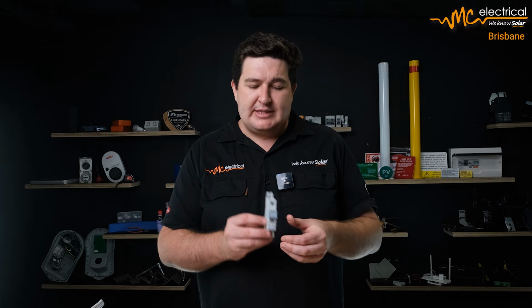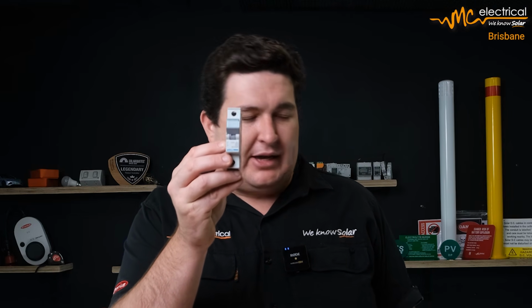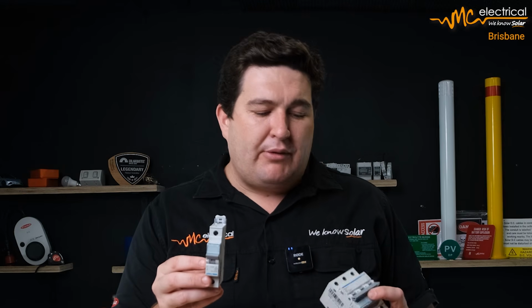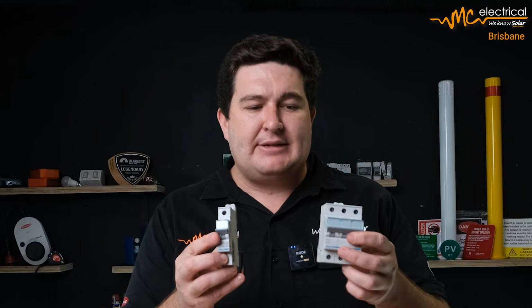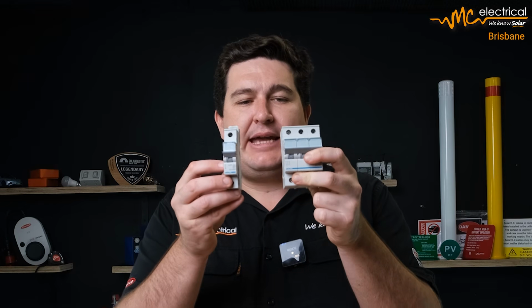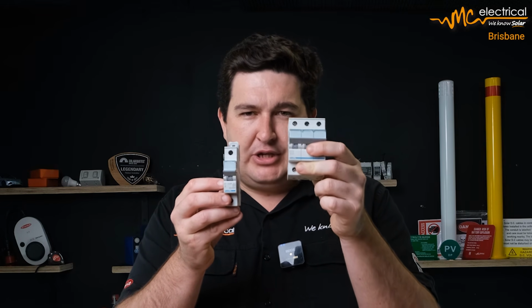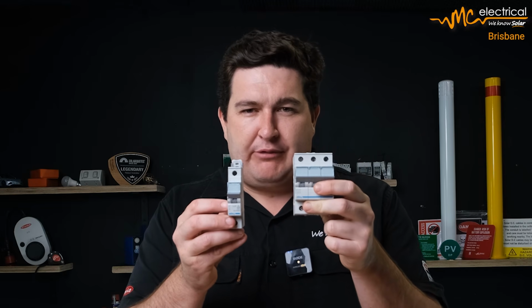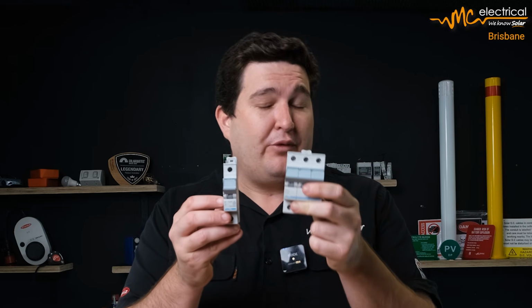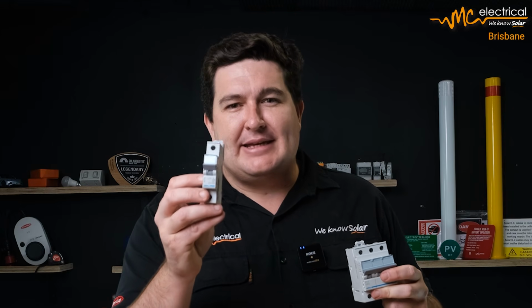A really good place to start is having a look at your main switch. So this is your circuit breaker, which will turn off the whole home. A single phase house will be a single pole. It'll look something like this in most modern homes. Now on three phase, because you've got 3 active cables coming in, you need basically 3 of the single phase units. So see how this is 3 times the size. Now, if you've got a big switch like this, you've almost certainly got 3 phase. If you've got it on an aircon, you've almost certainly got 3 phase. Otherwise, if you only see ones like this, you've basically got single phase.